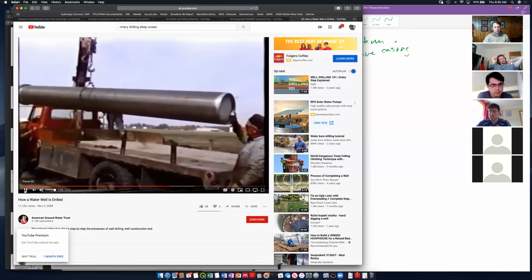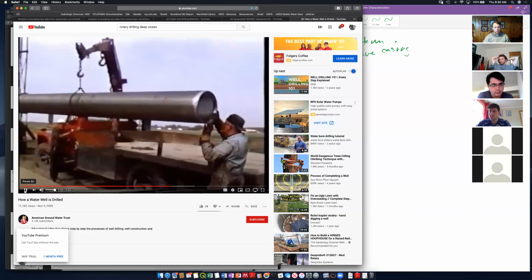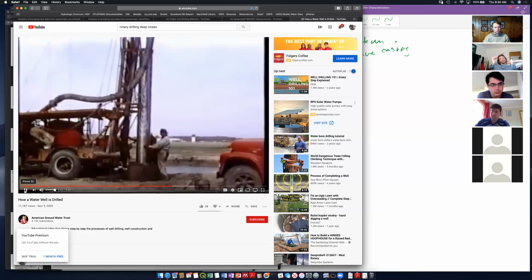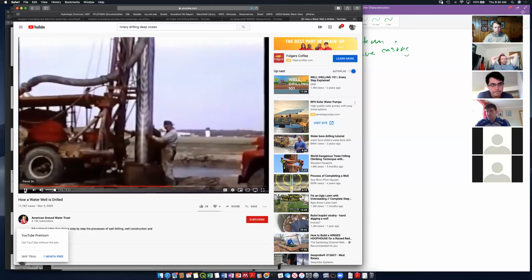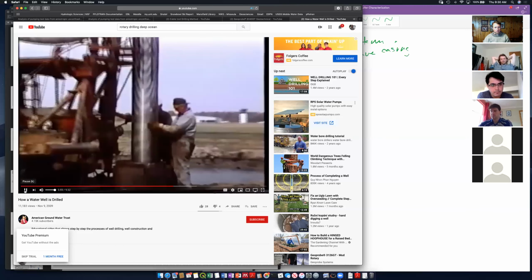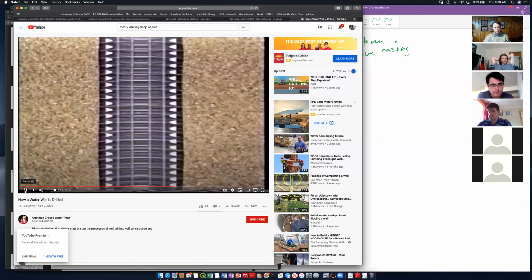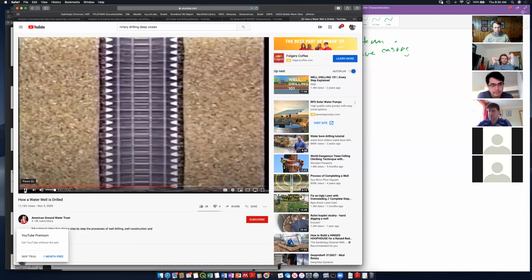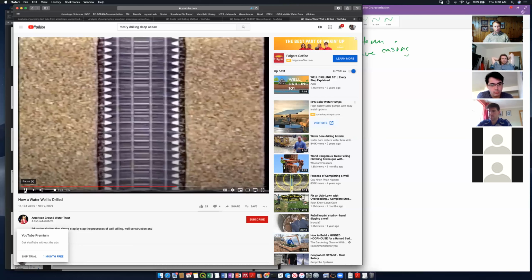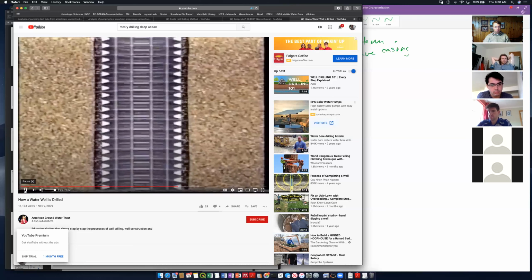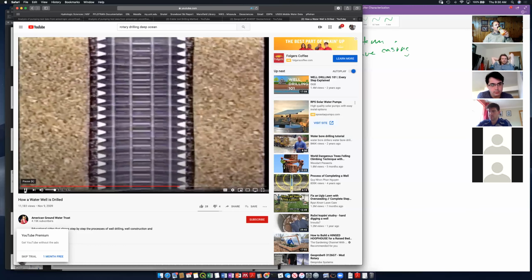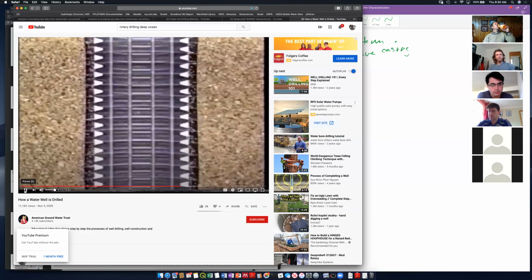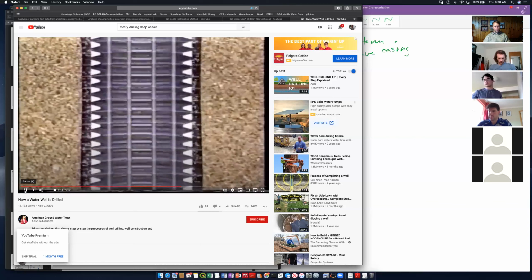If the well is drilled into rocks that are crumbly or into sands and gravels, a well screen probably will be needed. The well screen is a sieve or strainer-like cylinder attached to the bottom of the casing. It allows water to flow into the well while preventing fine rock particles or sand from entering. Well screens are not all the same, and the well driller will select the opening size of the screen depending on the size of the rock fragments or sand that make up the aquifer.